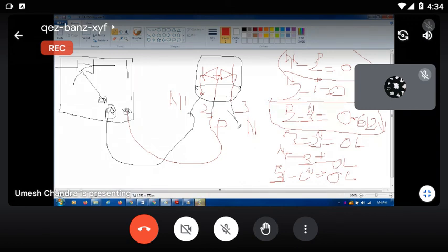Sir, isn't there any other method to find out whether it is NPN or PNP transistor? Any other method? No. Okay, sir. Actually, this method is very easy. Another method is for resistance. You just know the high resistance or low resistance. That is for identifying the emitter, base, collector. Actually, this procedure is easy to identify the NPN or PNP. Okay, sir.